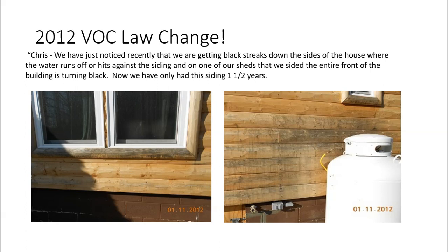And I was like, no, it totally doesn't need a 2-coat, because I had been using it for years, since before 2012. Well, sure enough, they changed the formula. That one word change meant the change from an oil to a film forming, which now required a 2-coat finish. Long story short, it failed after a year and a half, and it was completely my fault.